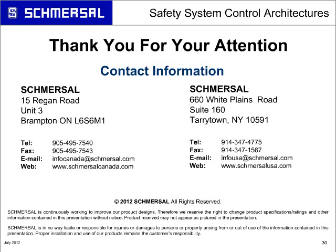If you design everything to control category 4, you've reached the highest safety level possible when it comes to the safety control architecture. Reality is, the best thing that you can do in any situation is take a step back, look at the machine, identify the functions on the machine. You have an e-stop function, you have a guard door function, you have a muting light curtain function. What are the functions on the machine? Identify each one of those functions and determine what level they really should be at. You can get out of control with safety very quickly. You want to be safe, but you want to have a practical, realistic approach to your design aspect as well.